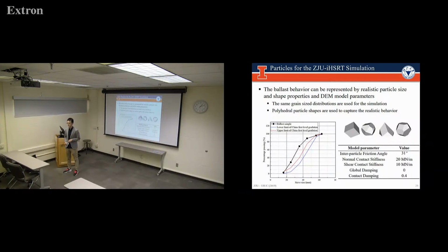But now I don't feel like we need to be even modeling that, because that's too much of a guessing game anyway. What we know for sure is how the gradation changes throughout the life. So why not pick certain periods of the life of the ballast with different gradations and understand the deformation behavior related to those, and bring those together. So I think that's the approach most of us are pursuing.